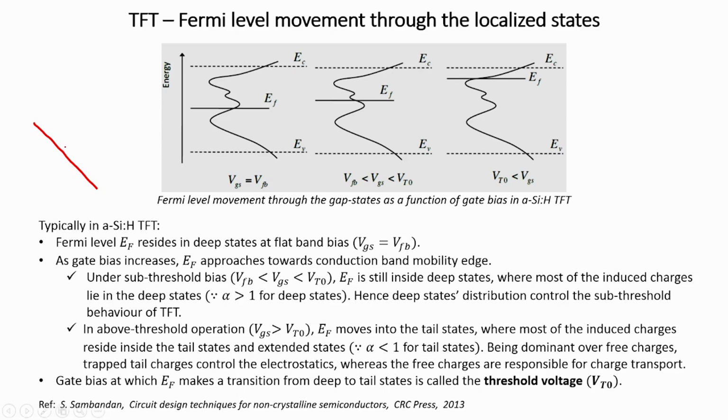So, in crystalline silicon we had a device structure wherein we had a doped semiconductor, an insulator and a gate, and the consequence of adding positive charge was firstly we achieved flat band, and then if you use a p type silicon body, we first achieved depletion.